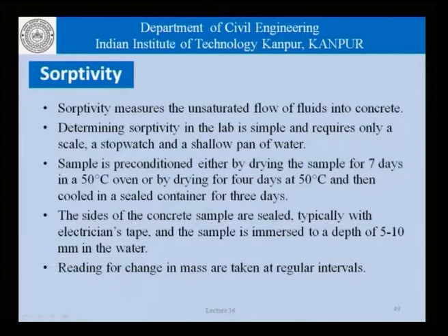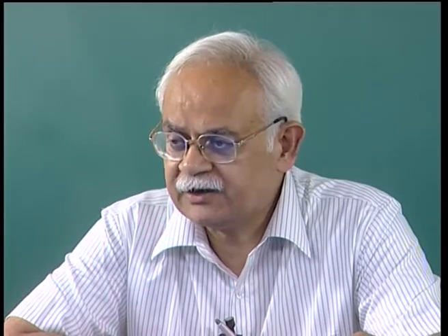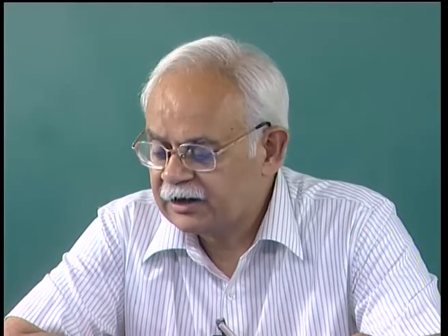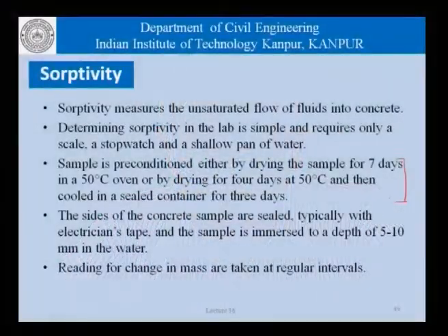Now, these numbers are all optional in the sense that only if we are trying to carry out a test under standard conditions do we need to follow this. If the test is being carried out for research purposes or for making a qualitative assessment of one concrete versus another, any of these conditions can obviously be relaxed. The sides of the concrete sample are sealed, typically with an electrician's tape, and the sample is immersed to a depth of 5 to 10 millimeters in water.